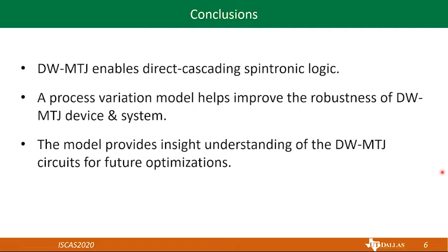And to advance the development of this technology, we proposed a SPICE-only DW-MTJ model with random parameter fluctuations that supports investigation of robustness of DW-MTJ systems to process variations. The error rate of the DW-MTJ 1-bit full adder is evaluated with Monte Carlo simulation using this model, and this model also enables the identification of the most critical device parameters and input signal combinations, thereby providing understanding necessary for device and circuit optimizations for robustness and efficient operation of DW-MTJ computing systems.